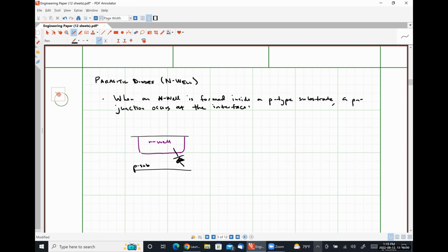In CMOS circuits, the substrate is usually tied to the lowest circuit voltage. So we usually keep the body or substrate at ground. And what that means is that if the N well has any potential whatsoever, our device is exhibiting reverse bias characteristics, and we have some depletion layer capacitance, right?